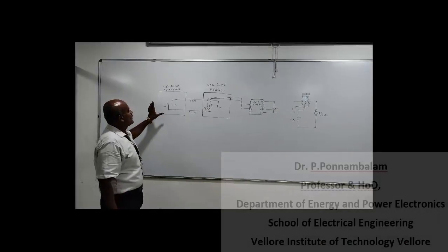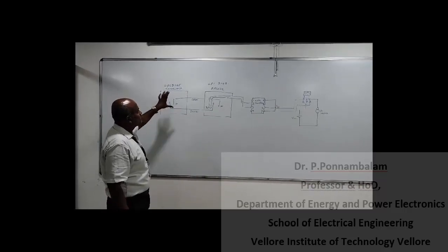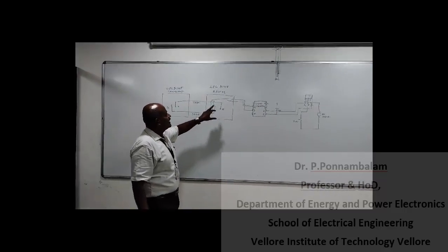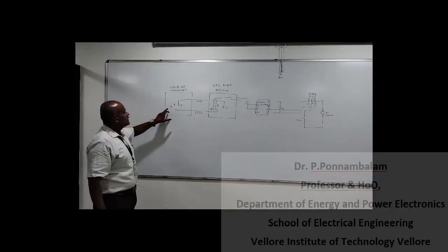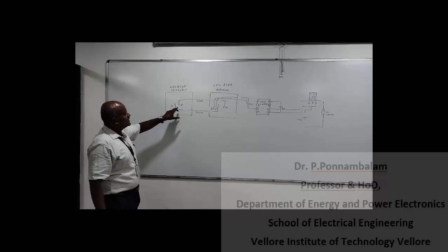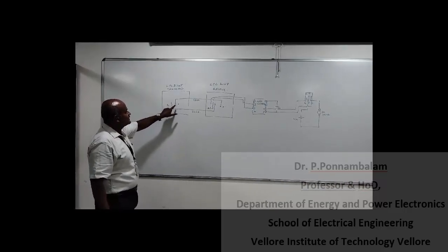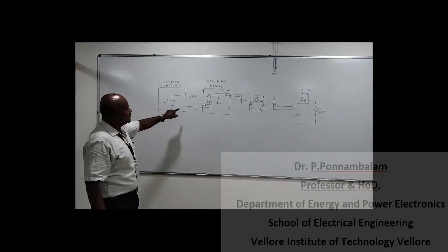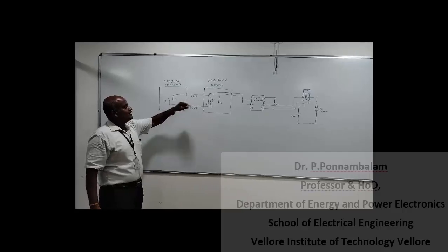So this is the LPC2148 where we have dumped the transmit program, and this is the one where we have dumped the receive program. So here from the J2 junction, we are taking the 6th and 10th pins, while 6th is your serial clock, and 10th is your serial data.